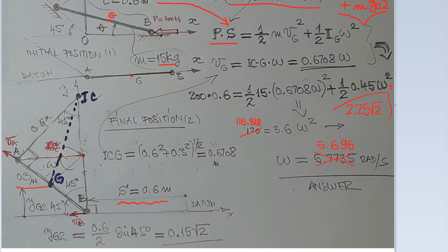So we have a right angle triangle with a 45-degree angle. So this definitely has to be 45. It means it's an isosceles triangle. It means that the distance from A to the instant center is the same as from A to B, that is 0.6 meters. So in order to find the velocity of the center of mass, we need to calculate...